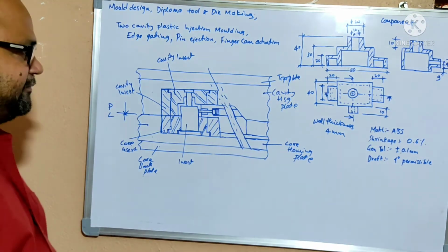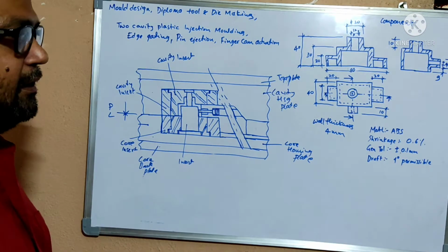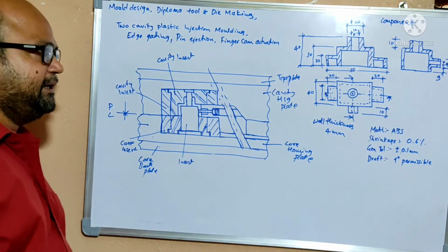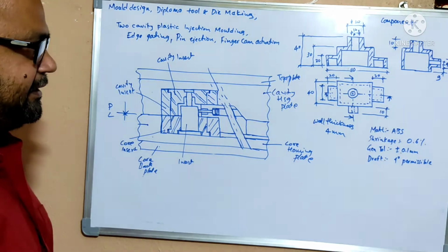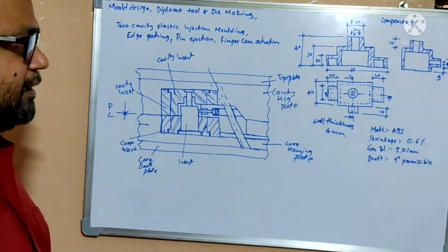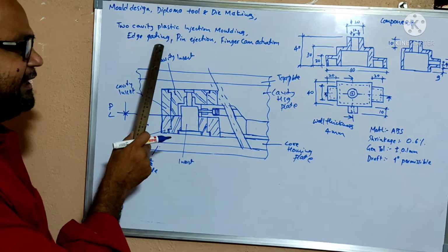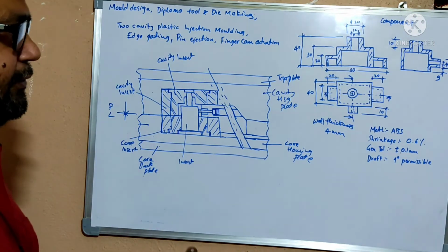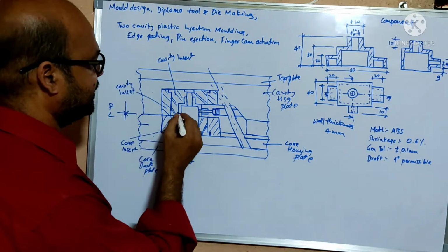You are observing here, when I place molten metal through the feed system, it carries through the sprue and runner, which is the modified trapezoidal runner, and through the gate, that is the edge gate, you will fill the component. I am showing this.